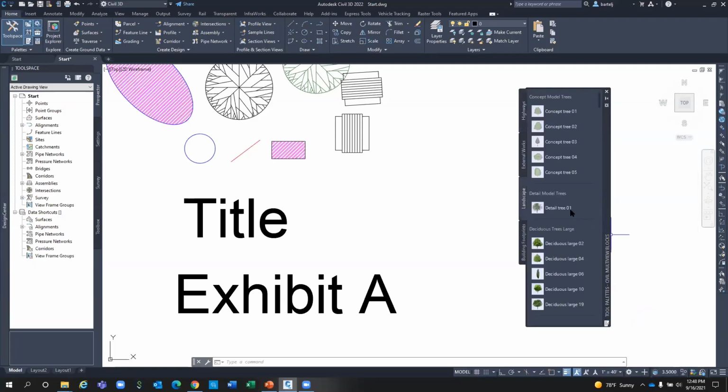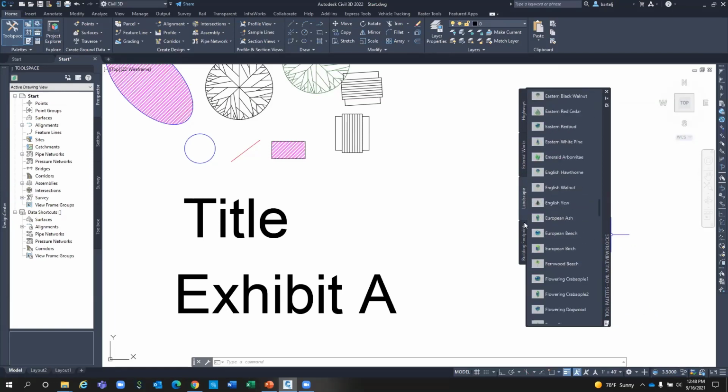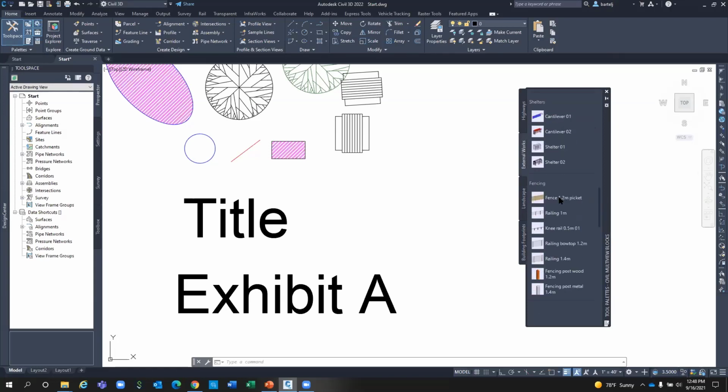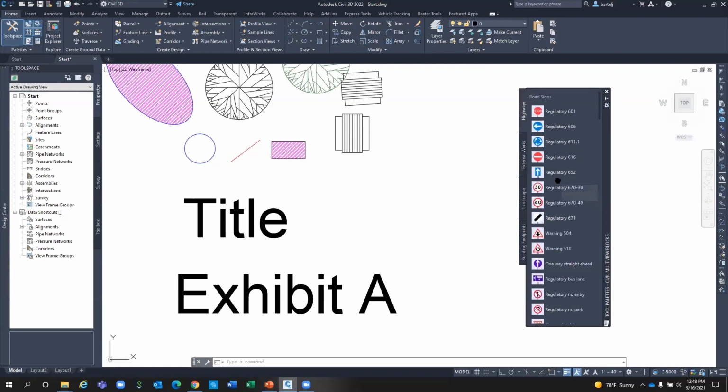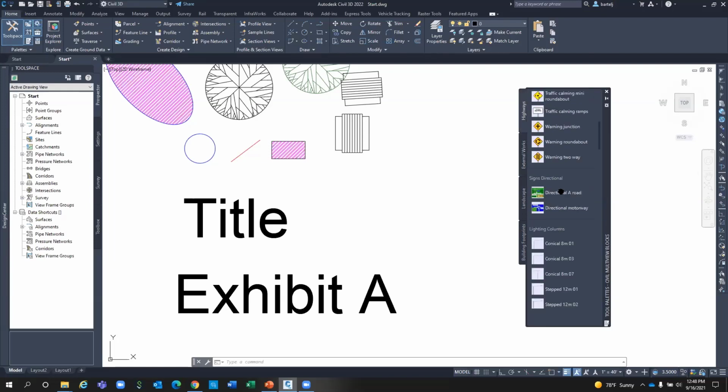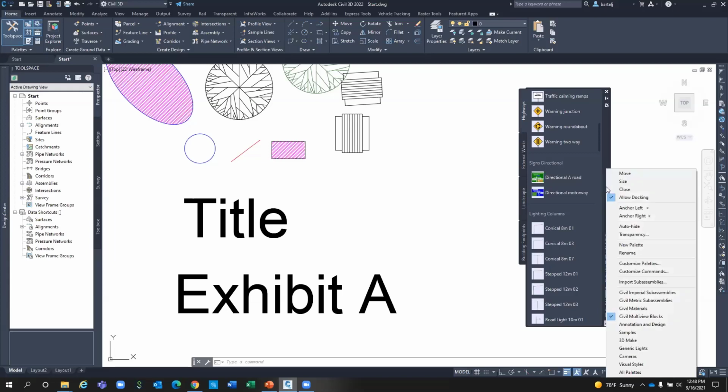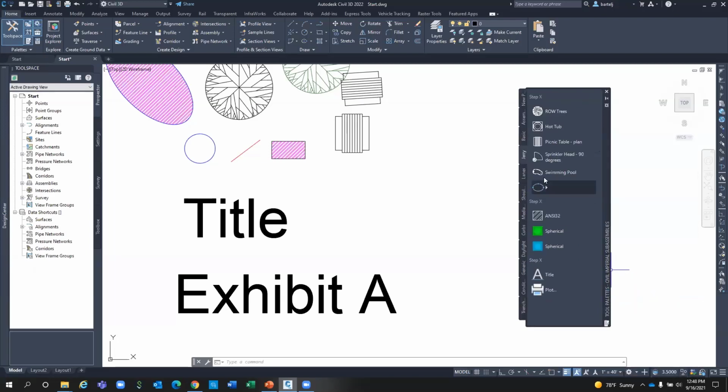If you've not poked around in here, very powerful stuff in here. I mean, you've got tons of landscaping things with trees. You got building footprints. You got park benches, playground equipment, fences, different utility poles, signage, all types of stuff that can be done with this. But these are grouped into different collections of palettes, or what's a palette group. So what I can do, I can select the ones that I want because this is where I created my palette. It's part of the Imperial subassemblies.